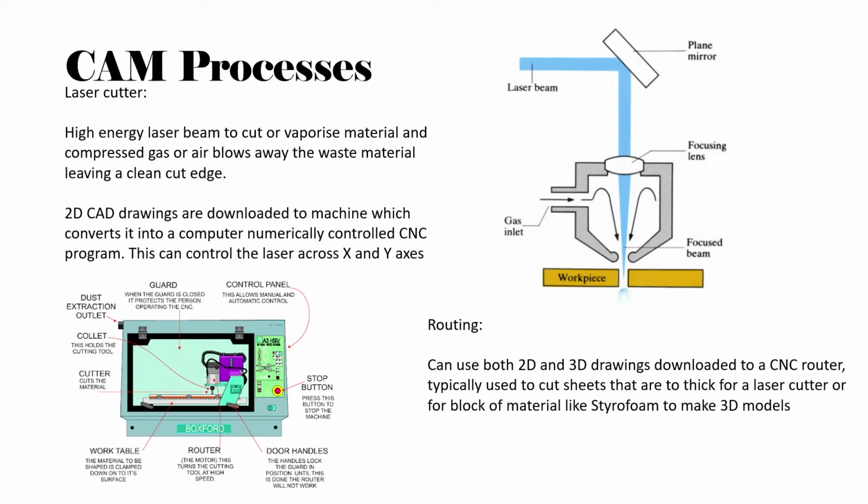So what happens is that a laser beam essentially is used to cut the material. So you have a compressed air. We have a CO2 laser in college, which are the most common ones. It's water cooled. So at the back of the laser cutter, there's a laser tube that essentially sends a laser beam through. And what will happen is the laser beam essentially hits mirrors.